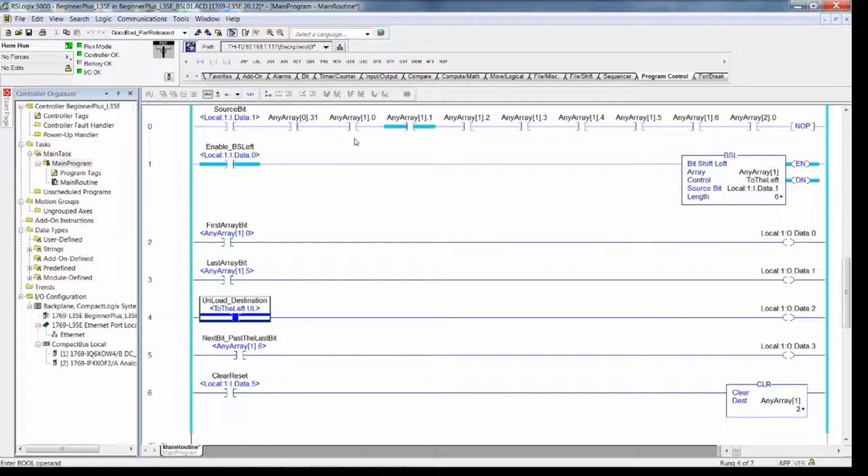Now I have push buttons and toggle switches wired in parallel. We're using the universal digital field device simulator to do our lab projects with. I can choose to use the toggle switch for a maintained on-off, or I can use the push button wired in parallel with it, which functions not only as a normally open, but also as a normally closed.